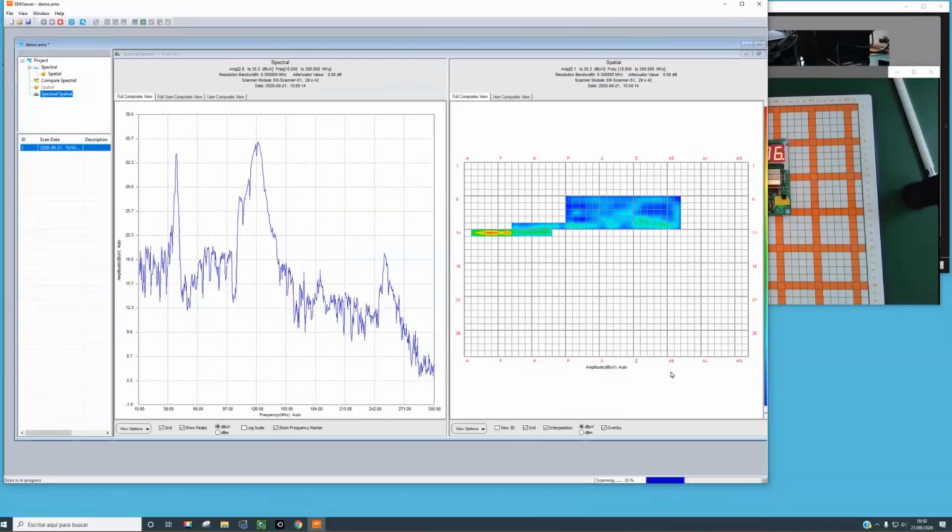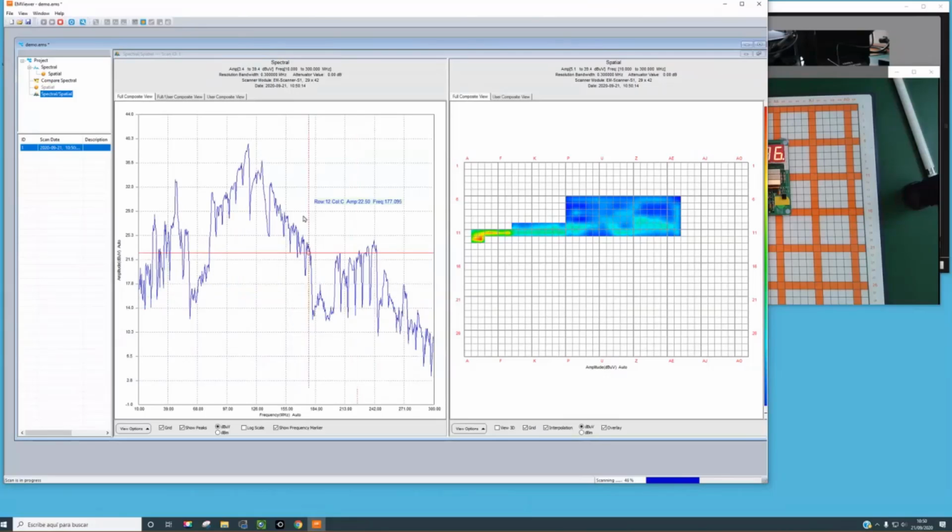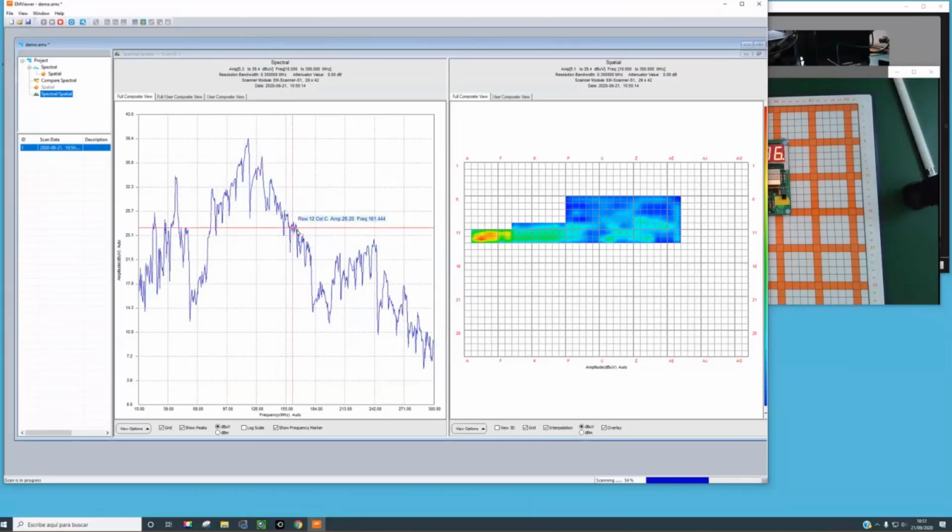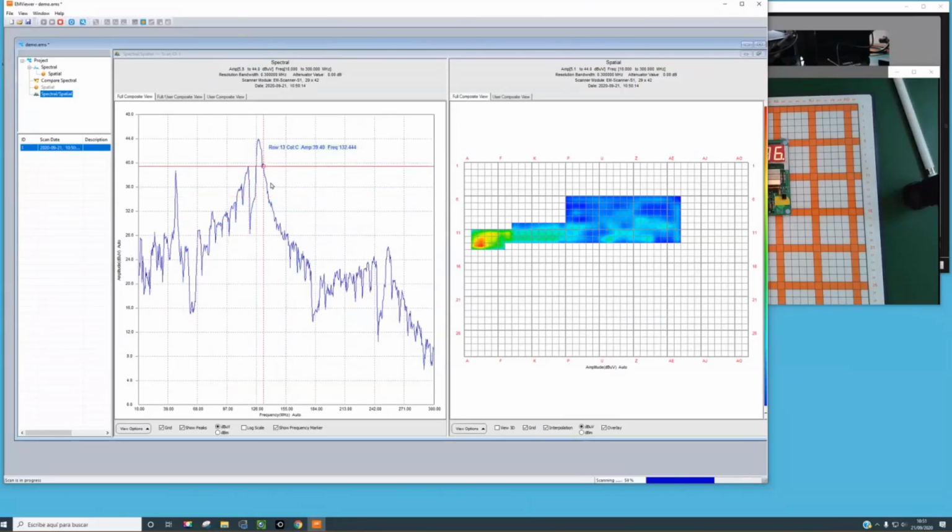You can see that in frequency, we start to see a mountain in the area of 125.26 megahertz. This is the area that I was radiating in my first measurements with the scope and the antenna. So in some area of my circuit, I am creating this electromagnetic energy.